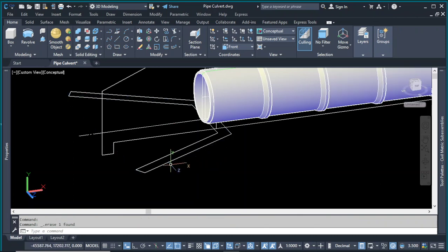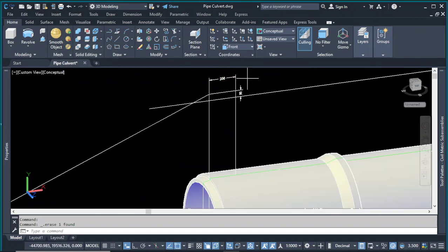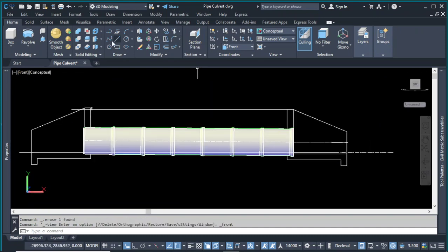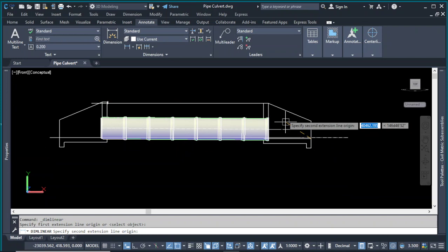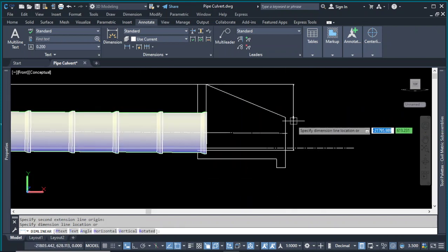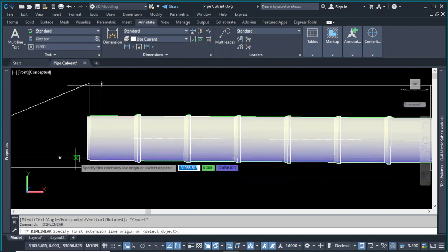The other thing we need to be able to do is to make the wall. If we go back to the front view, we want to know how high is the wall. So let's do measure. You can get this height, and I think it is 1,500. Carry the same here.